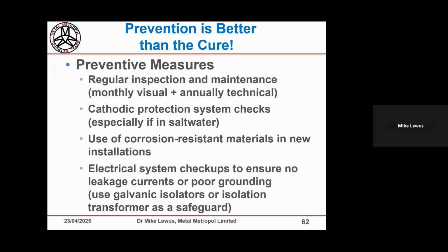In freshwater, you typically use magnesium because I'd probably have to check this. I do know that there are specially formulated anodes, but the general rule of thumb is that in freshwater you typically use magnesium anodes, whether it's a formulated magnesium anode or not, because the water is not as conductive, so you need a higher driving voltage to protect your parts. So it comes down to that in terms of the material in fresh water.